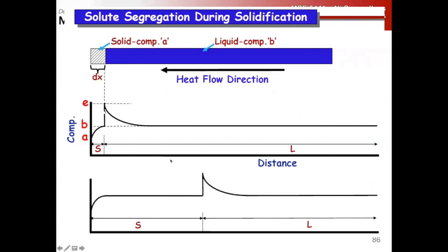How high purity silicon was made. The patent on zone refining, pushing the solute out by taking a moving heat source and moving it along and selectively partitioning solute atoms to the liquid phase repeatedly, right? The patent on that paid for the operational cost of Bell Labs in its entirety for the whole time that